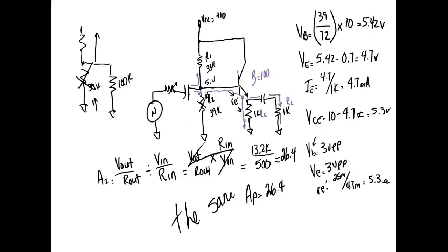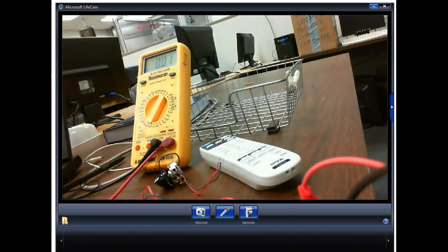Come up here, get my meter out. Going to take my common and connect it to circuit common. Okay, where's my other meter lead? Here's my base voltage. Here's VB. Got it turned on. Let me open the resistor first. Here's VB. Can y'all see? Supposed to measure what? 5.4 volts. Measuring 8 volts, which is what we expected.